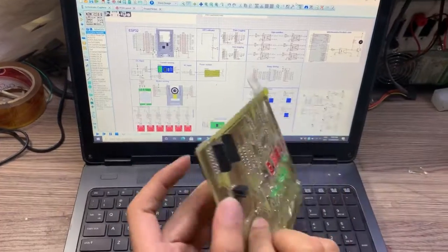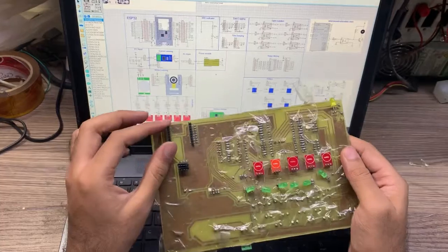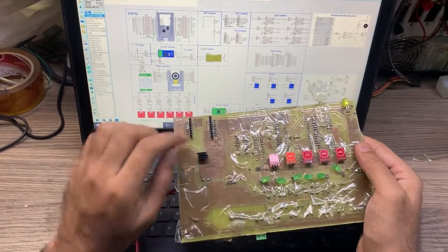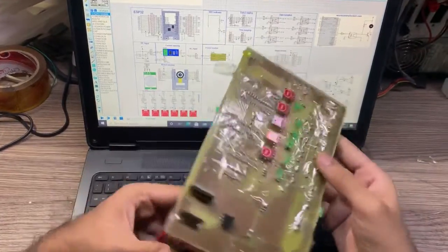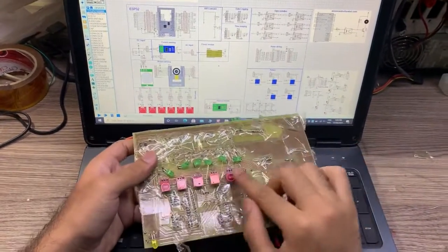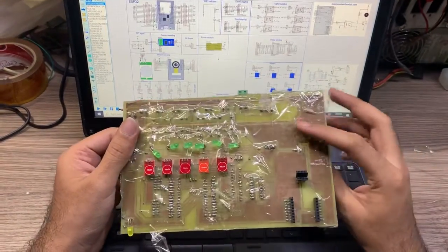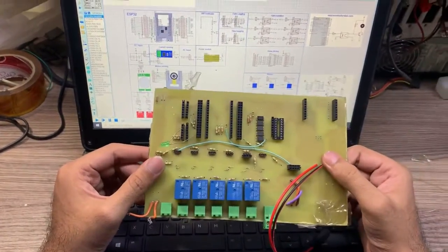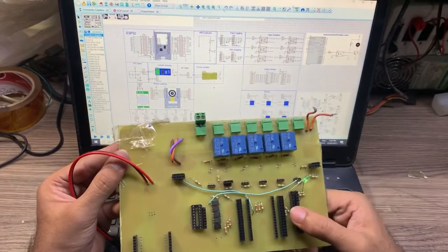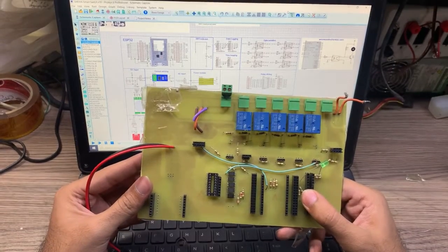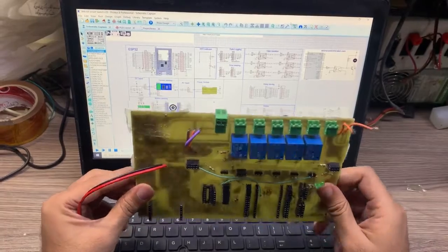And over here, now this is a 2-layer PCB, front and back. Over here we will attach the ESP32 cam, and over here the PIR motion sensor. These are the touchpads like I mentioned, and the dimmer module was connected separately via this port. This was the prototype we developed, and it was pretty much functional and working, but we improved the circuit, made it smaller, and then we developed it via JLCPCB. That I'll be explaining in the next video.